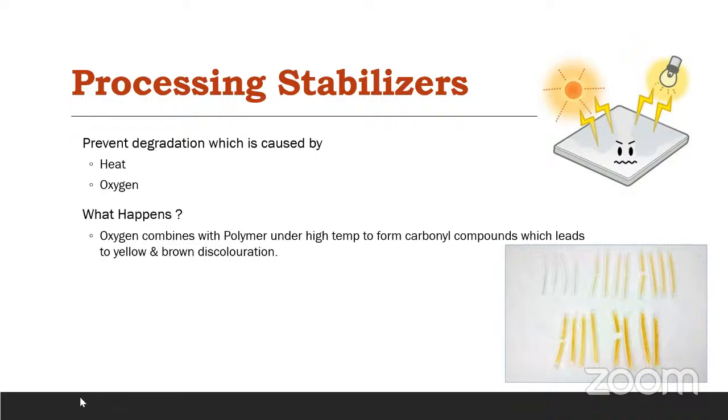Then previously halogen based flame retardants were being used, like if you see polyvinyl chloride, due to the presence of chlorine atom in polyvinyl chloride, it also gives the flame retarding effect, okay. But the chlorine atom or the halogen which is present generally affects the properties of your material and it impacts the environment, okay.